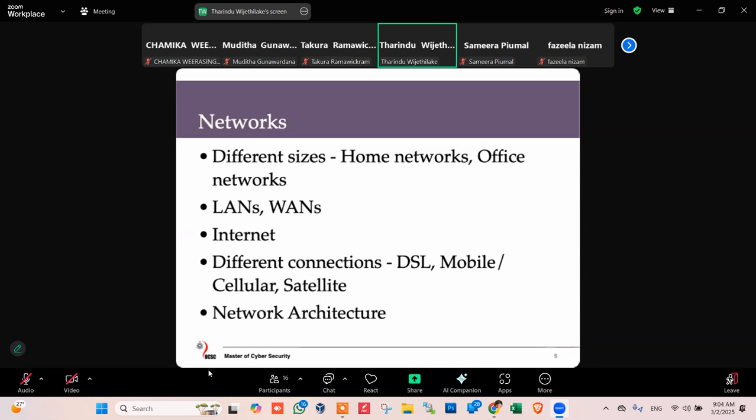For example, you give one channel to voice communication, several channels to the uplink, and several channels to the downlink. Likewise, you separate the medium into different channels and hand over different responsibilities to each channel. With that, people were able to do voice communication and data communication in parallel, and they were able to get higher data rates.